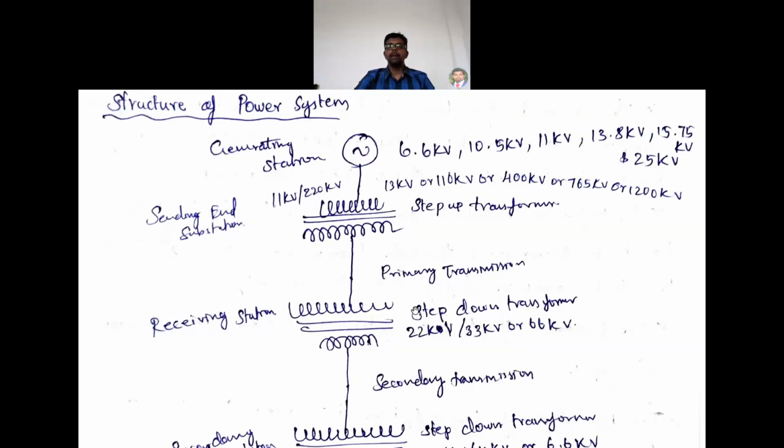And again, what we are doing is we are stepping down, like 400 kilovolt by 220, and sometimes 220 by 110, like that. In between, that is a switching substation. That is called switching substation. Say for example, if you are traveling a long distance, you will be finding that switching substation. That size might be of 440 by 220 kilovolt or 220 by 110 kilovolt, like that. It depends on your usage and how much distance it may travel.